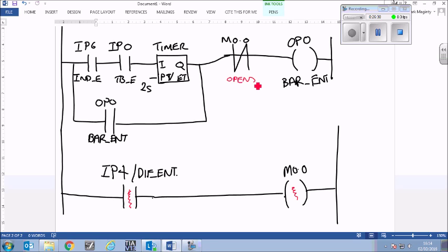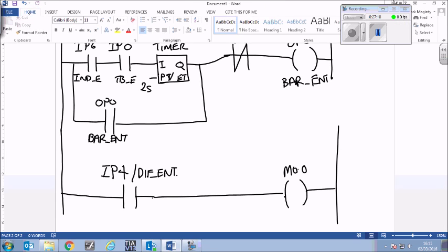Well, not closes. Not quite. Well, it's not open yet. We're at stage 1. Car's outside. Yeah, nothing's happened yet. So the car arrives, you press the button, 2 seconds delay, it stops there because that's open. That there can't operate, which means the barrier can't go up. So by using that as a normally open contact, we can never get the barrier to go up anymore. Okay? So what most people do, which is fair enough, is they go along and say this here should now be a normally closed.